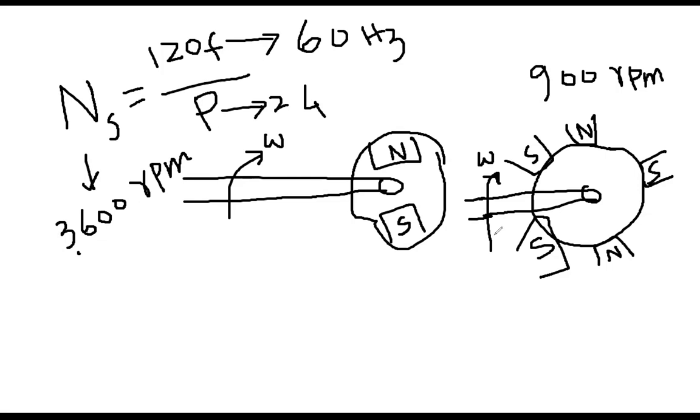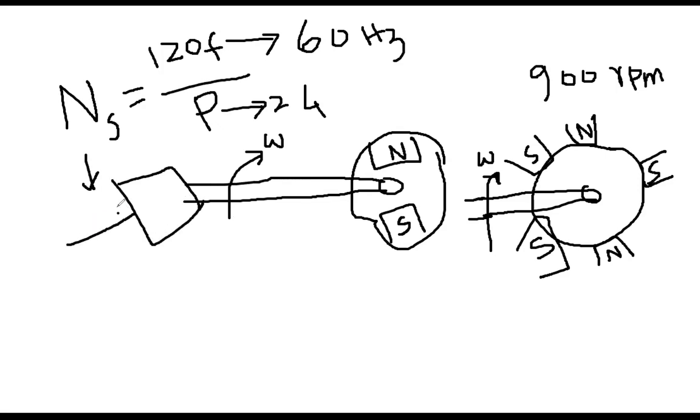Now everybody, you all know gas turbine, nuclear turbine, steam turbine. Typically they use this system because this shaft is ultimately rotating with the help of the prime mover. Prime mover means the turbine. The turbine is connected here, and the fuel input can be coal, oil, gas, etc. Typically they have very high speed. That's why this system is preferred, because it rotates at higher speed. Let's say 3600, and you have to maintain the frequency 60 Hz. So what should be the pole number? You cannot use more than 2 poles here.